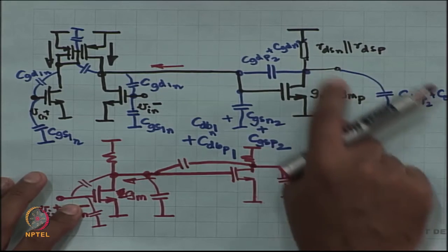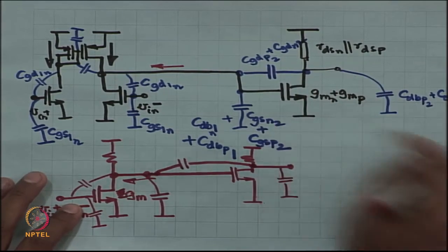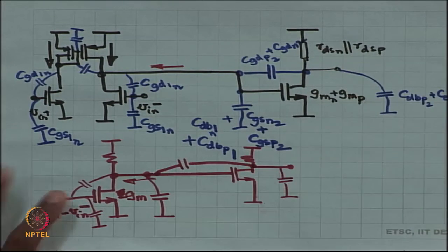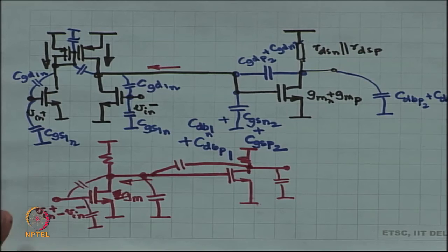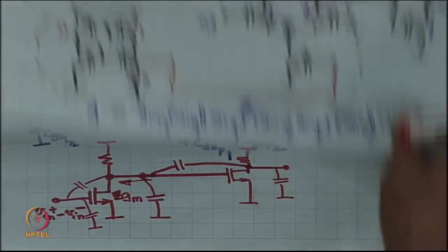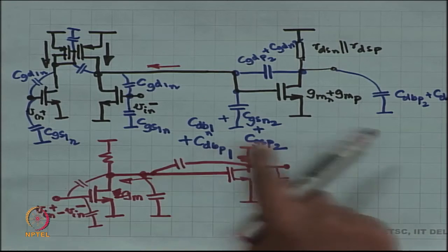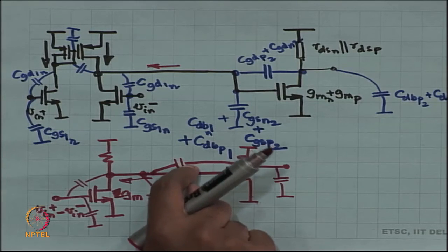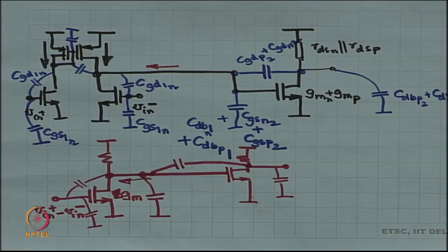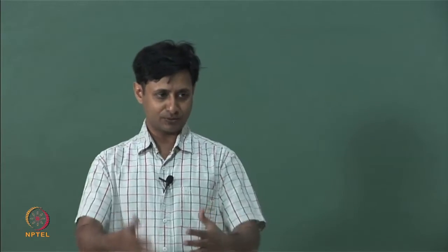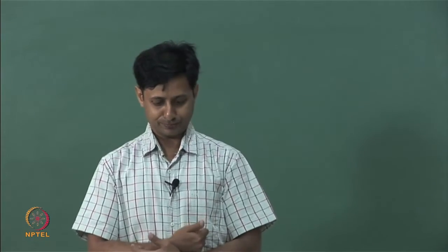Okay. So, this looks like a diode connected transistor. So, we figure out the first pole and the second pole. The ratio of these two poles has to be as specified by the phase margin and the DC gain. So, with DC gain and phase margin, we already know the ratio of these two poles, and that will give us how much this extra capacitance has to be. Fine. Now, this is the methodology. I am just trying to go through the entire methodology.